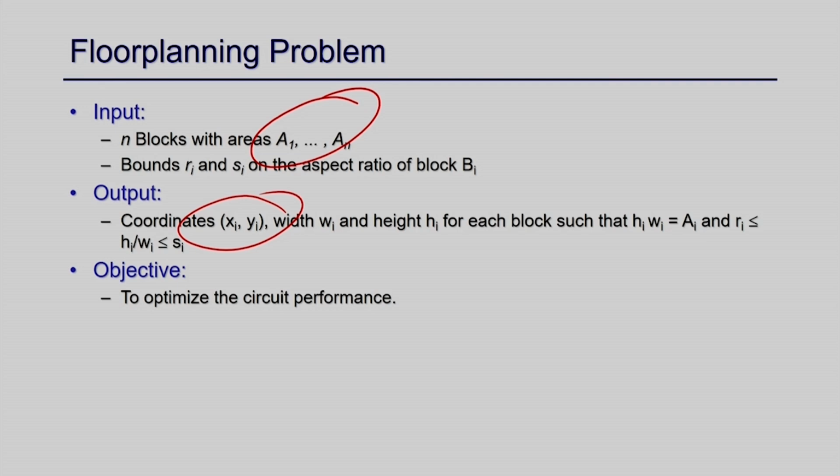There may be a little bit of movement of the blocks so that your total wire length is minimum, or you can also reduce your total area. But after placement, the position of each block is finalized and you cannot have any other change. Then the only thing left is making the physical interconnections, right. After floor planning, it is possible to exchange some block positions or move them to other places without changing the die area, with the objective of reducing the number of interconnections and total area. But after placement, you cannot have any option to move your positions, right. This is what happens after placement.